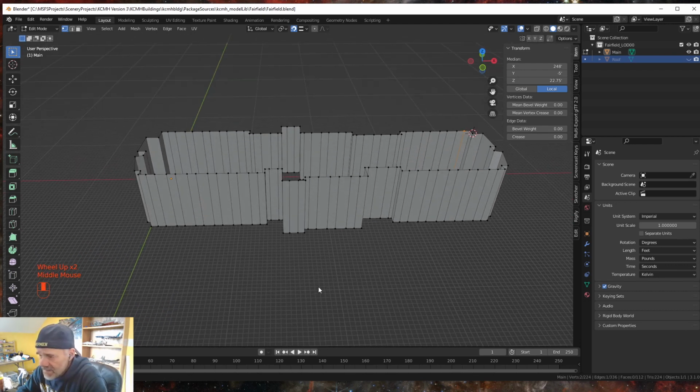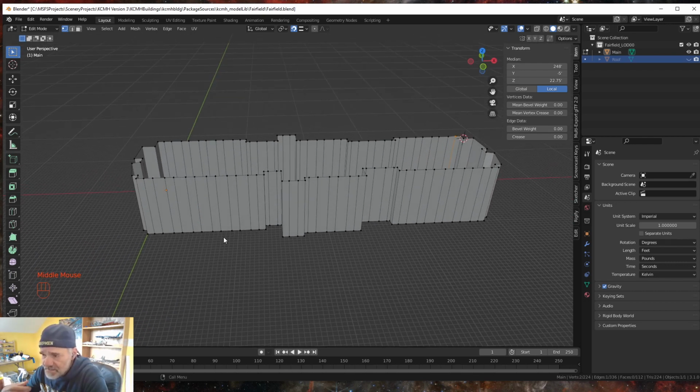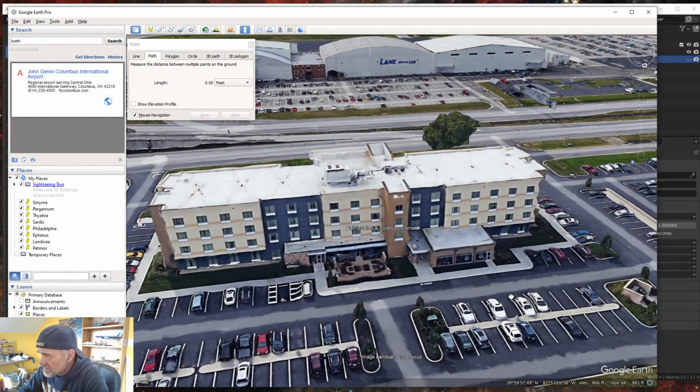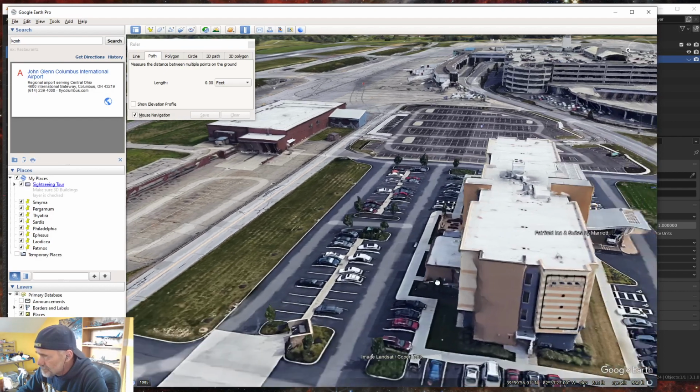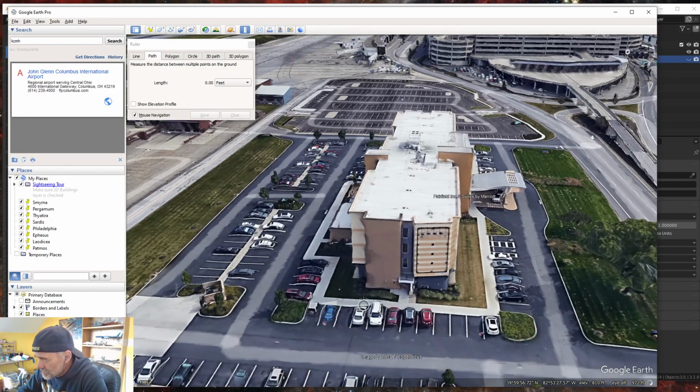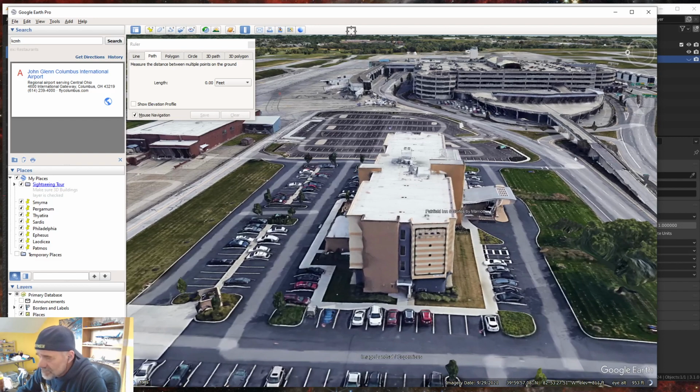All right. Now we want to create some loop cuts. Well, we can go ahead and do our windows on the ends too. So let me do that real quick. So let's bring up our prototype and let's swing around. And over here on the end, okay, we'll do a measure from this big one here to this corner. 3.79.